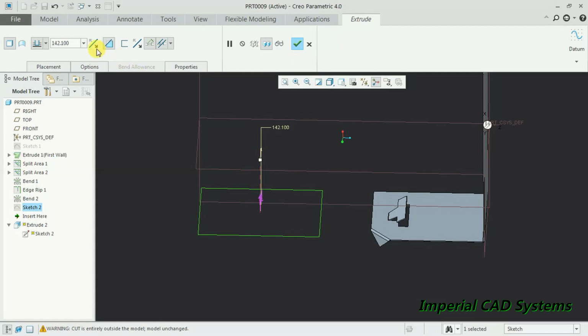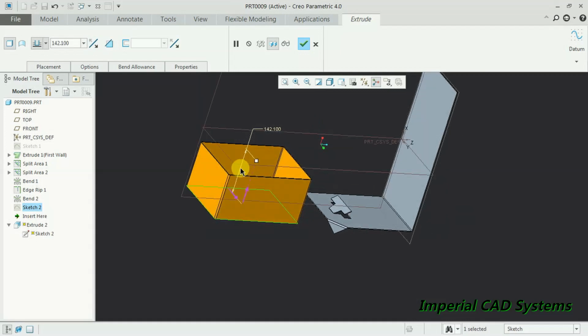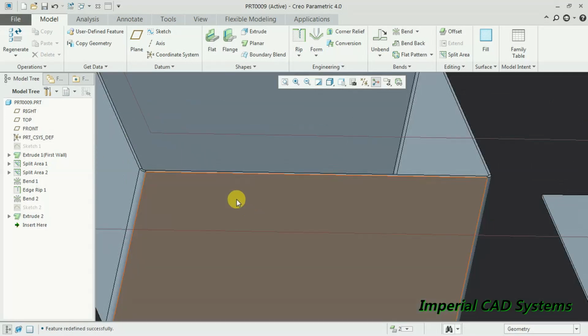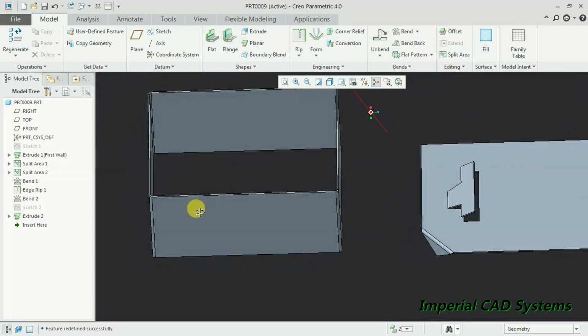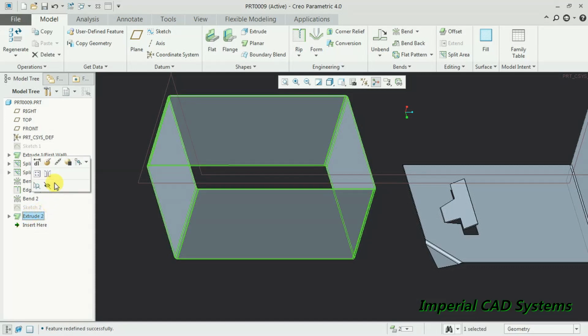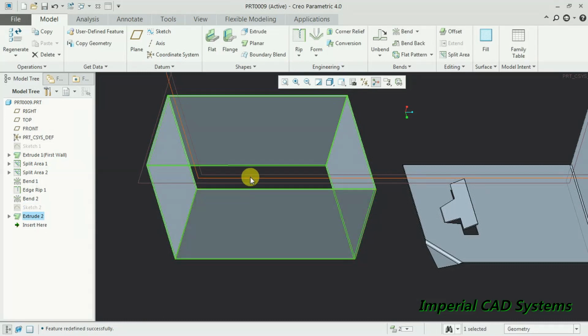With some thickness. I reverse this. See, we got like this. Then of course bend radius also you can see here. While extruding, you can see here fillet also applied to the sharp edge. If you don't want to apply bend radius, then go for extrude, edit definition. Here in option, just check out this radius option, then we get sharp edges. See, like this.